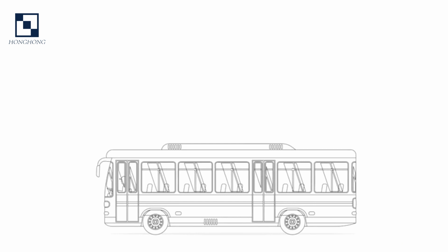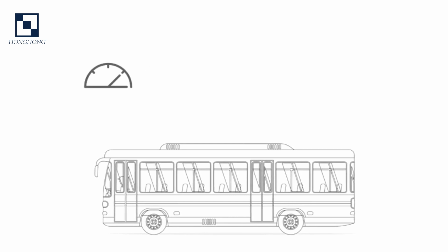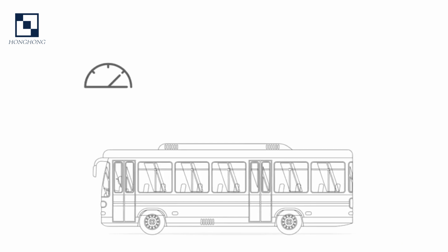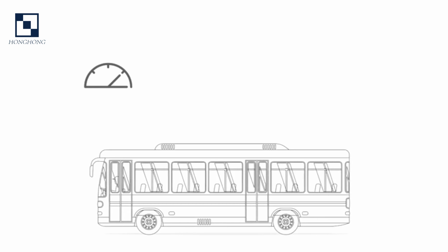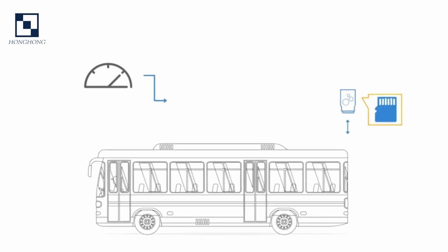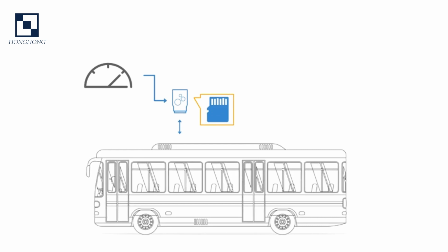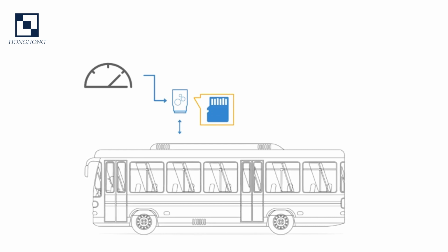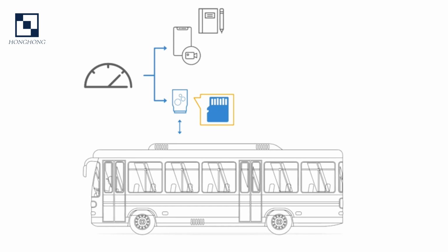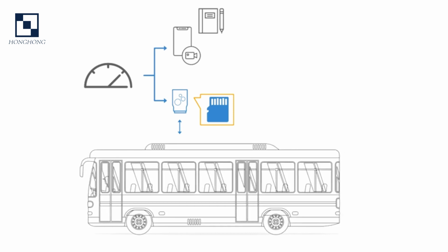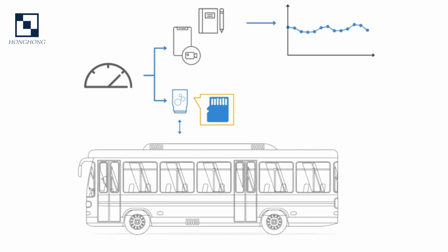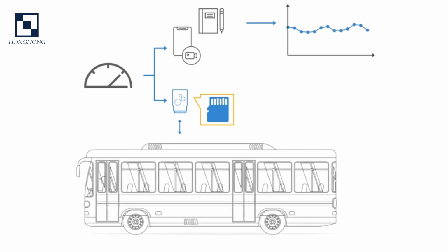If instead you need to reverse engineer a continuously changing CAN signal, such as a state of charge or engine speed, the sniffer view is less well suited. For this type of use case, you can instead log data to the SD card of a CLX0001 during a trip, while noting down the physical values from your car's dashboard over time. Using, for example, Excel, you then create a benchmark plot of the signal values from your trip.